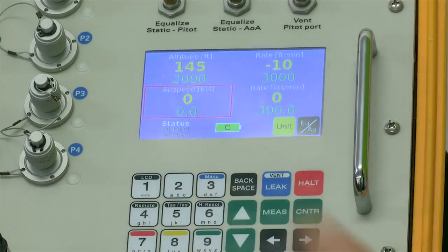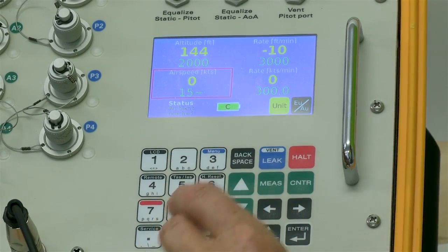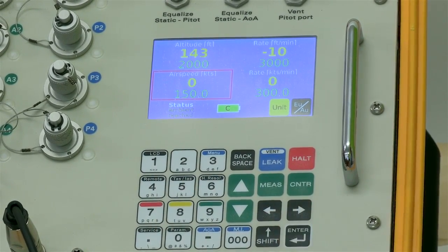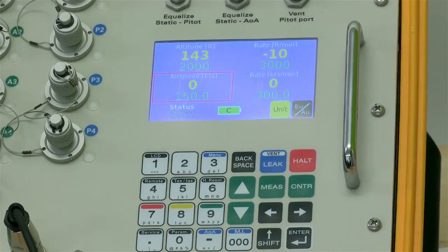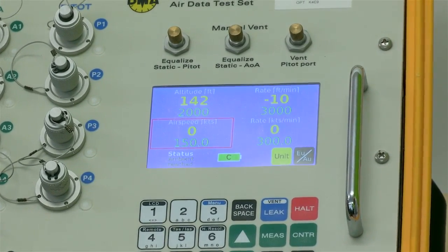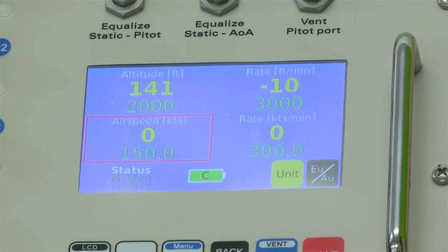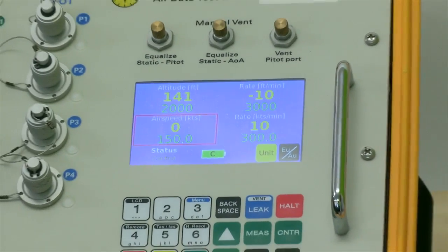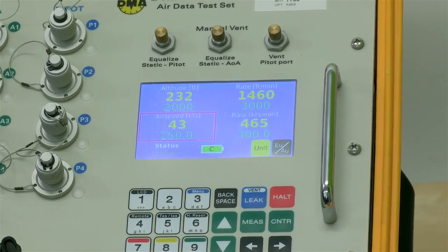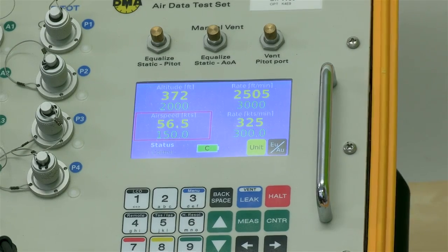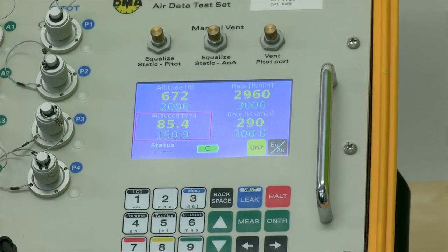We can then move down to airspeed and put in some desired value for that. Let us say 150 knots, enter. Nothing has happened because at the moment we're actually in the measure mode, having come out of the ambient search situation. So to now go to those values, we go to the control key, and those two values will now begin to be approached. We have a rate of 3,000 feet per minute as the default, but you can change it to your heart's content, and we have 300 knots per minute for the airspeed.